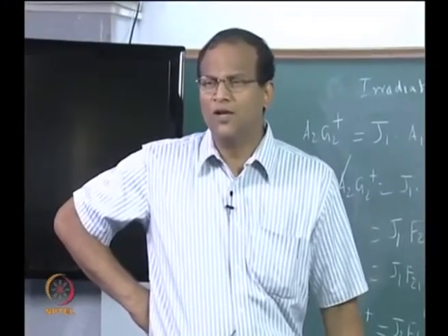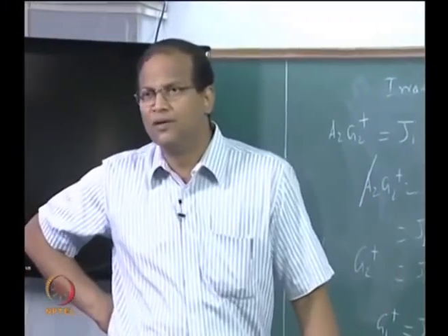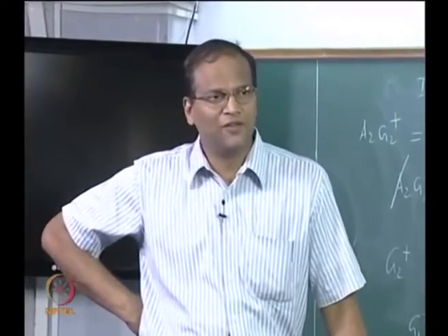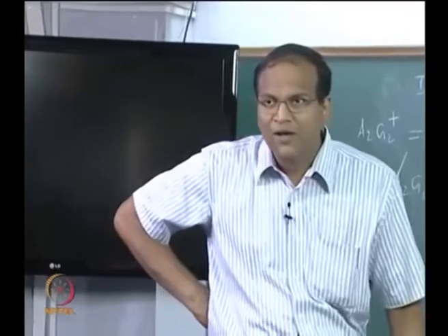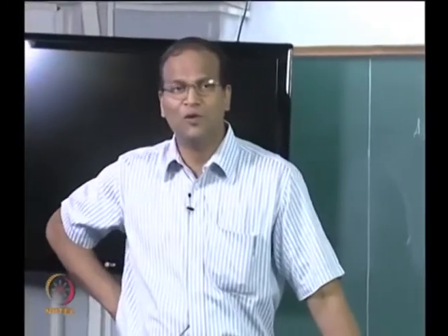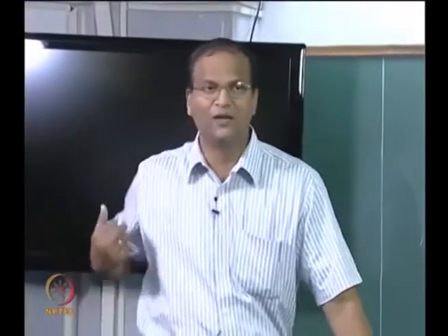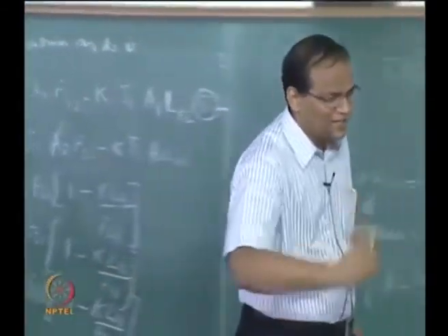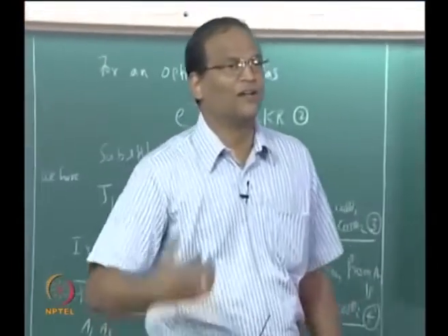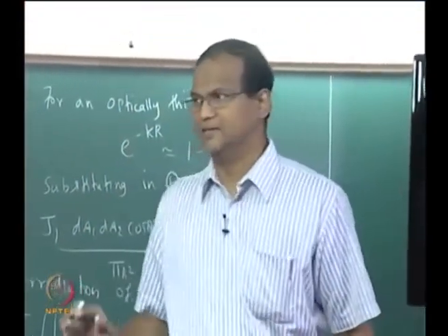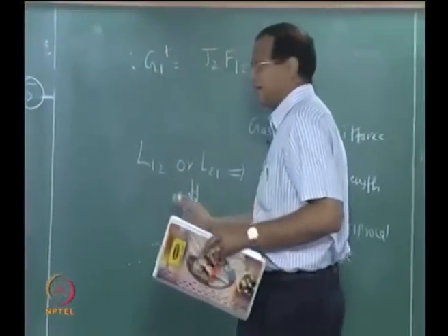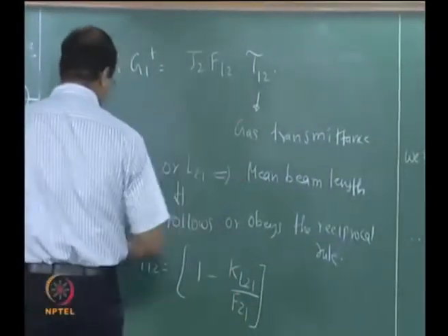So when you have to work, you can already conjure up visions of how to solve this gas radiation problem. You will write the radii first, you will calculate the view factors. After calculating the view factors, you will put in the mean beam length and calculate the tau ij's. And then the tau ij will multiply the Fij Jj, it is attenuated or reduced because of the influence of the gas. Okay. Now, we have defined this tau of the gas. So, this is basically I can call it as gas transmittance.